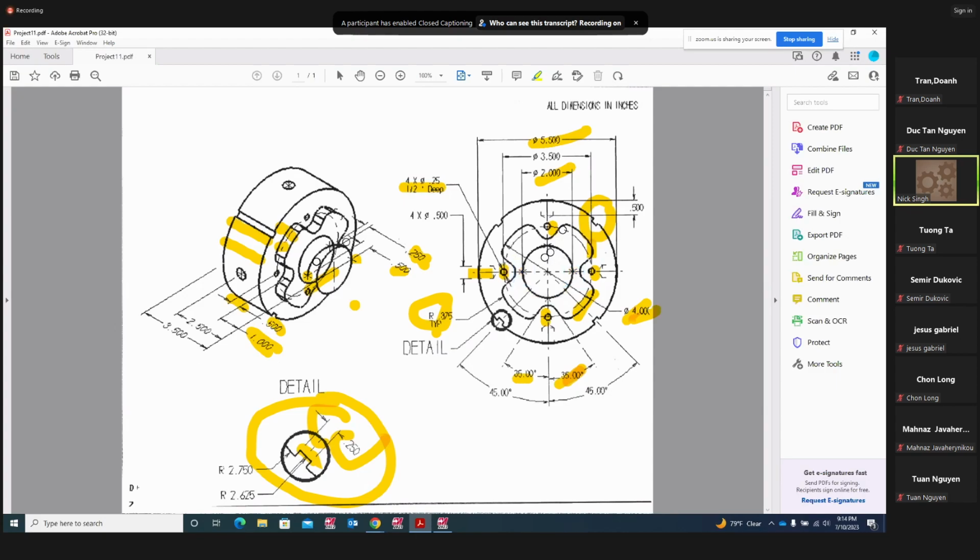And those 3 points, if you look right view, there's 1 point right here. There's 1 point right here. There's another point right here. Those are the 3 points. And if you look into this view right here, there's that same point over here. So that point is going to be on construction plane right. The first point, this guy, is going to be at X 1 inch, Y 0, and Z 0.